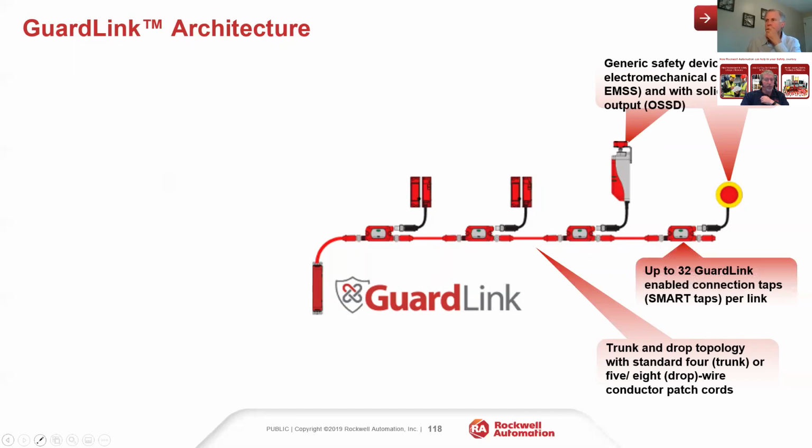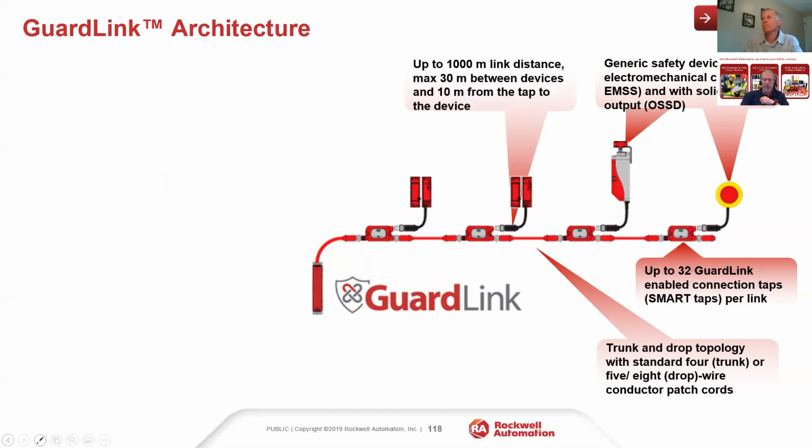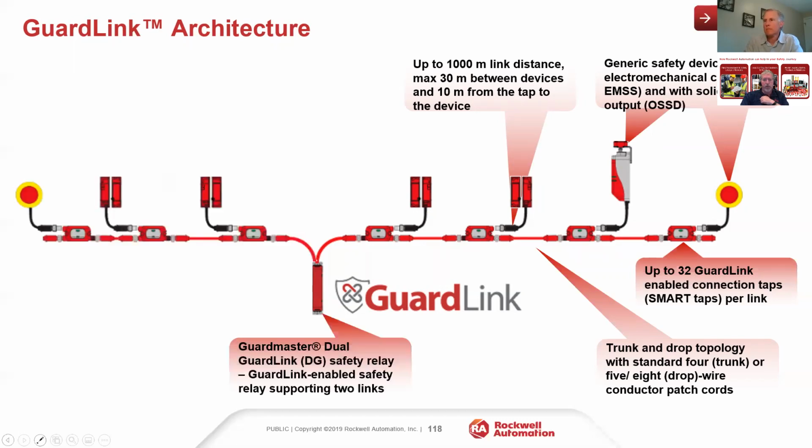You can have up to 32 smart taps per GuardLink, or per link, let's say. And you can have 30 meters in between devices. So if you do the quick math, you end up at about 1,000 meters in terms of length that you can have. That's a long way. But each one of these GuardMaster dual GuardLink relays, the DG relay, has 2. So you can actually have 64 devices and 2,000 meters worth of length.